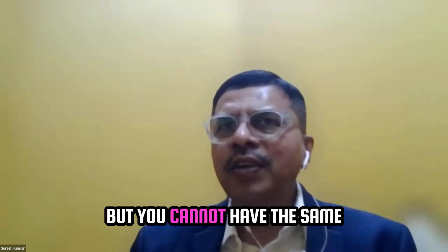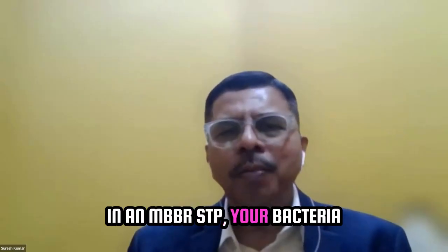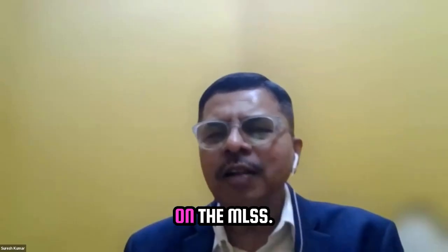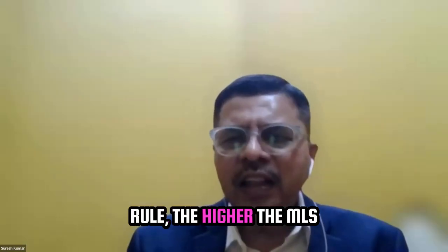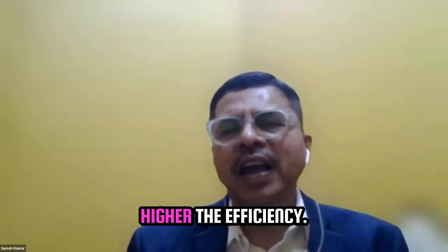But you cannot have the same formula in an MBBR STP. In an MBBR STP, your bacteria is attached to the MBBR media. It may not be present on the MLSS. So MLSS is not always a measure of bacteria content, but generally as a thumb rule, the higher the MLSS, the more the bacteria. The more the bacteria, the higher the efficiency.